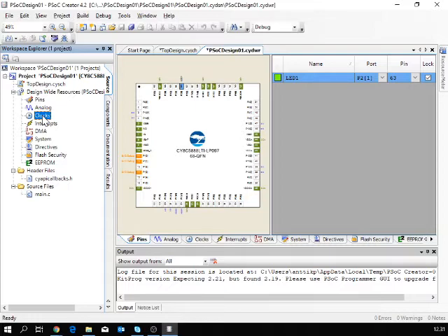If we had some bigger memory requirements, then you can use the DMA controller there. For example, communications. The DMA is one way to make sure that if you have a burst kind of data communication, you save the data somewhere else and let the DMA work, and at the same time your processor can process something else.